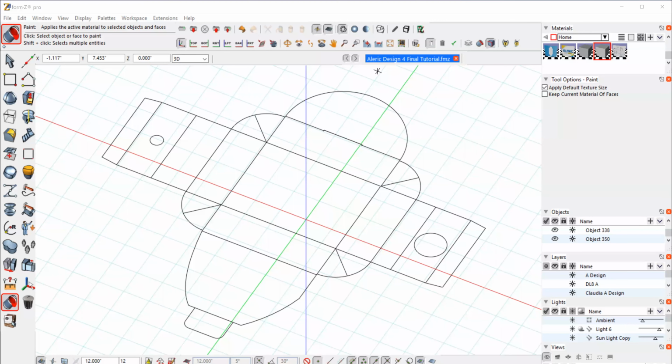Yeah, I'm going to review finalizing the die line for our folding carton. The die line, after it is fully developed and we've tested it like we did, is the final specification drawing for a folding carton. After we made our samples and maybe made some modifications, we now know that this is going to work and it's ready to go. So we need to dimension it and use different line qualities to communicate how this will function.